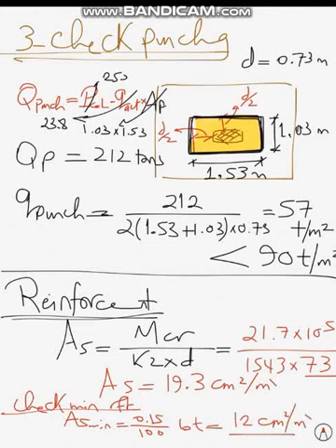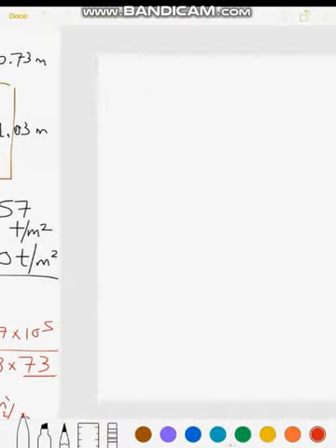So I need to convert this value to number and diameter as in the reinforcing RC course. I can use here 8 phi 18 per meter run, and it's not fixed. You can use, by the way, the number ranges from 5 to 10 and the minimum diameter is 12. You can use 6 phi 22 if you wish. It doesn't matter. You have only to exceed the required area.